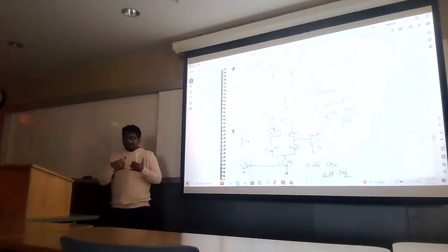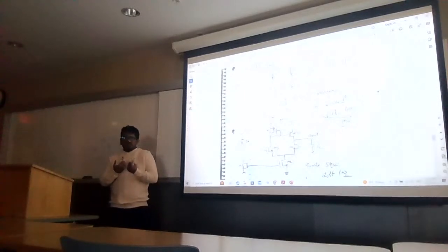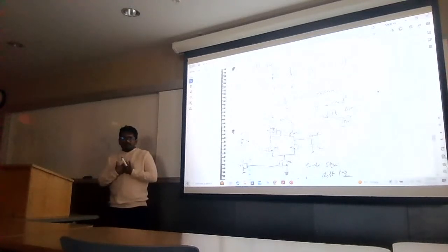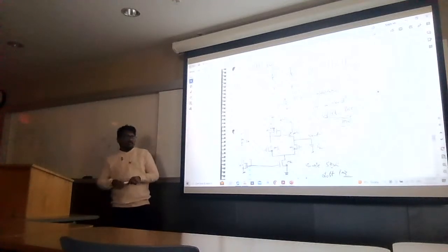Let's say an ECG recording system. The frequency of the human body signal is, I think, less than 2 or 3 hertz, and the amplitude of the ECG signal is 500 to 600 microvolt. Whenever we are dealing with this type of signal, it's too noisy. Let's say you are connecting some electric wire there, so noise comes from anywhere. So this differential pair can reduce this noise.